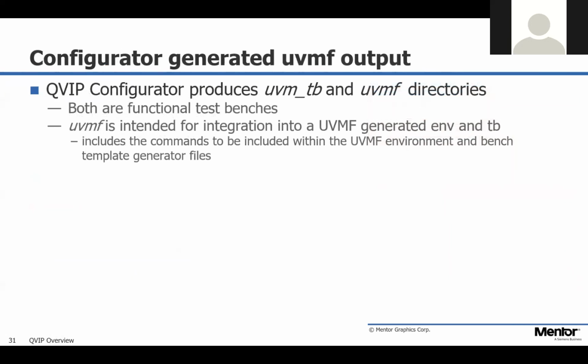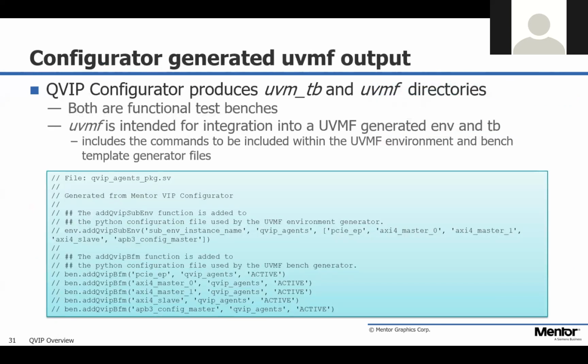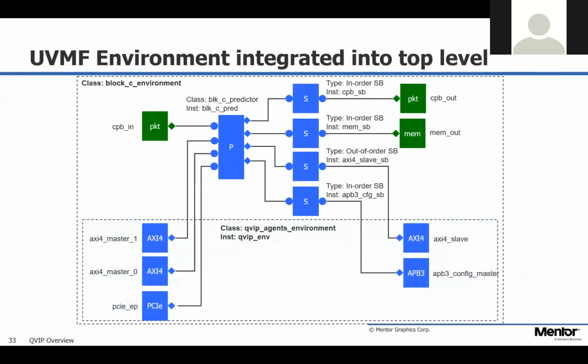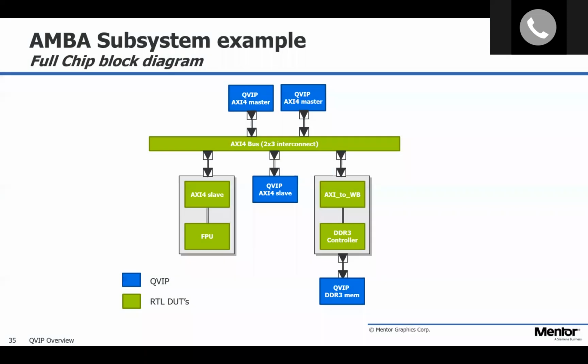agent for that protocol. We also give you the set of data you need to say, okay, I want to drop that environment. So I created this sub-environment that had a PCIe, a couple of AXI buses, an APB bus, a few of those things, and then it gives you the strings you need to put that into your UVMF environment so that you generate your whole test bench.